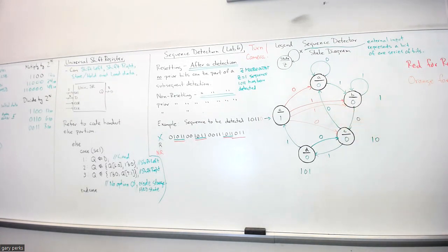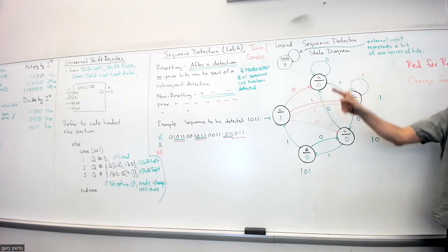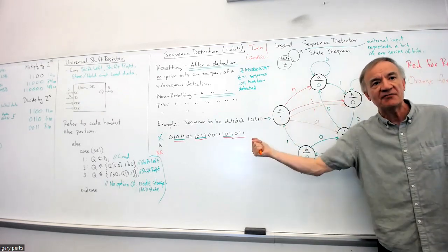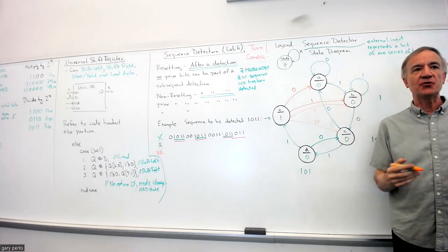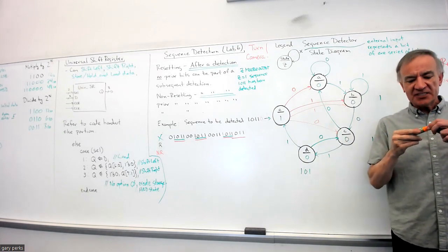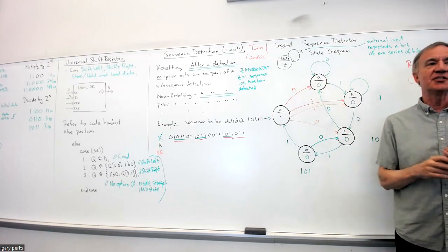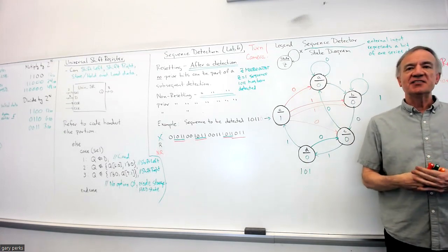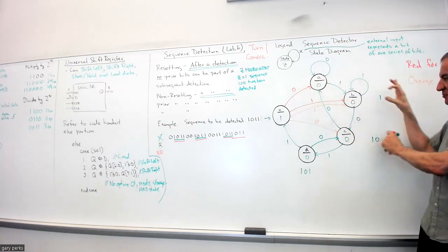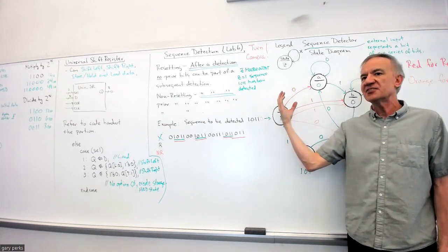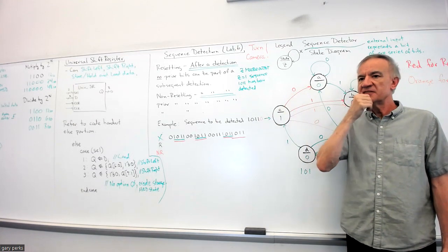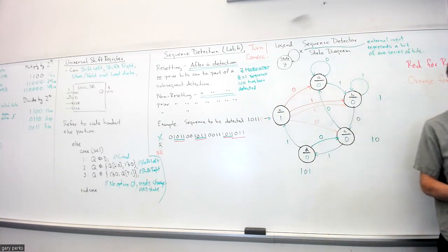What you see in black, red, and orange is the state diagram for the non-reset. Again, the difference between the two is what happens after you have a detection. Before detection, the state diagram is the same for both. That's the biggest mistake people make with these when they're doing state diagrams: they think there's some difference between the two over here, when no, that's all the same. It's not until you get a detection that there's any difference between the two.